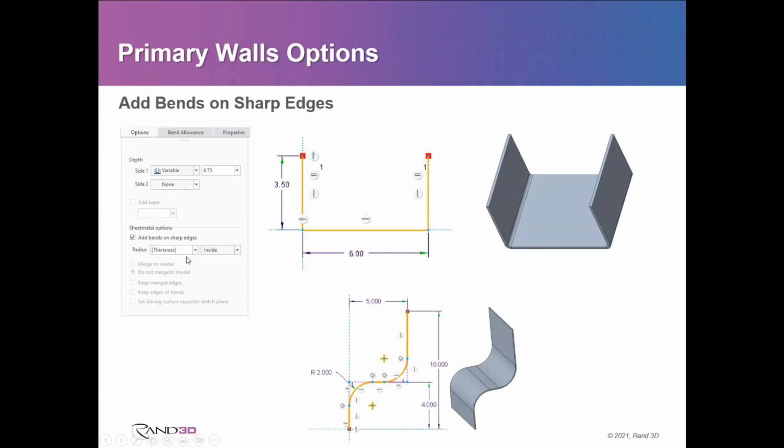And then all you would need to do is specify the size. So it makes creating the sketch easier. Now, if you wanted to, like you see down below, you could actually physically sketch the radiuses on there, but that's just more work. So I always try and use this option as much as I can, let the computer add the radius for me rather than try and sketch it out.